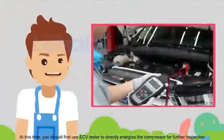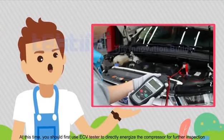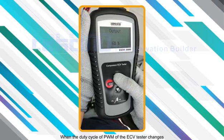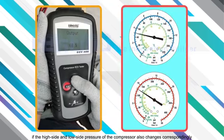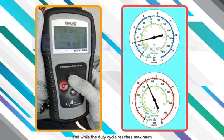At this time, you should first use ECV tester to directly energize the compressor for further inspection. When the duty cycle of PWM of the ECV tester changes, if the high side and low side pressure of the compressor also changes correspondingly, and while the duty cycle reaches maximum, the high side and low side pressure reaches the normal range, it is determined that the compressor is working normally.